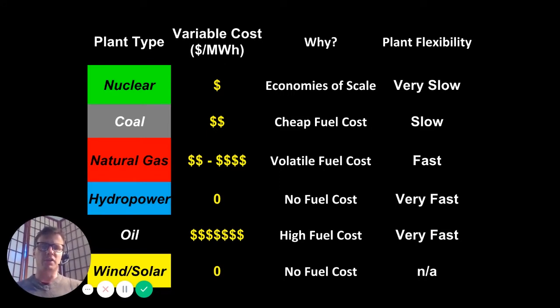We have this different mix of different generation technologies, each of which is associated with a different variable cost, in dollars per megawatt hour, of producing electricity. And in several cases, at least for coal and natural gas, those costs are directly related to the price of fuel. And there's this range associated with natural gas here because traditionally the price of natural gas has been very low, but also very high at other times. And so also depending on the mix year, you could have increased fuel costs.